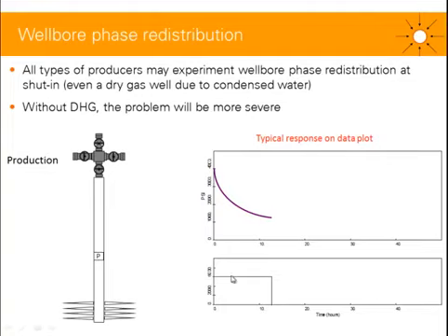So let's assume the well is flowing and pressure decreases this way. We've got a drawdown, and then we perform a shut-in. So pressure increases this way. The pressure at the gauge is equal to the pressure of the perforation minus the hydrostatic term, which is rho, the density, times g, the gravitational constant, times h, the vertical TVD height between the gauge and the perforation.